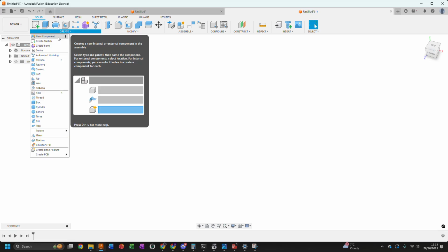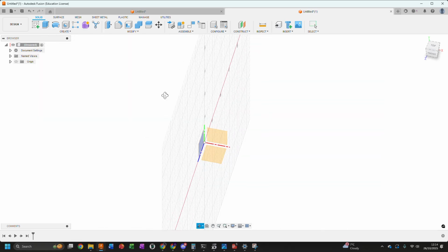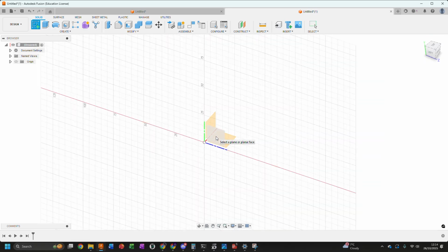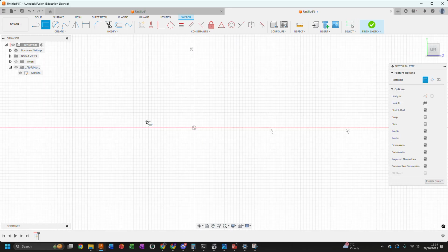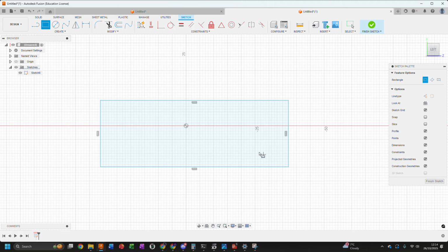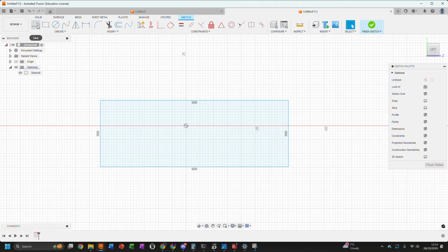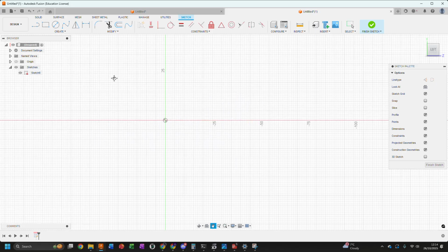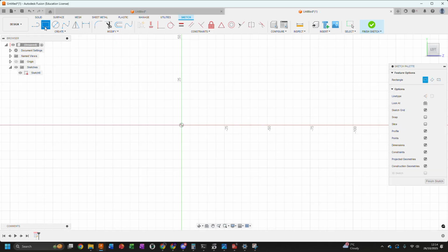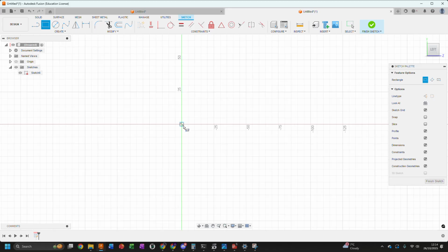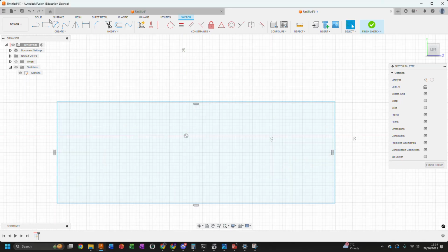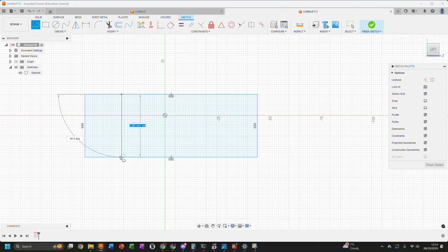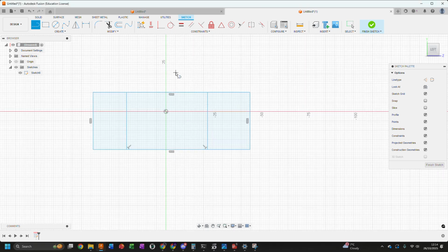So anyway, first of all, let's create our sketch and let's select this plane here, right? First thing we're going to do is create a rectangle, and we're going to create a line. So yes, I should probably have done that in a more easy to follow way. So hit the rectangle. It's in our sketch menu. Drag it. Now we've created a rectangle. We're going to create some lines now. So hit the line tool. Just drag it down like that.